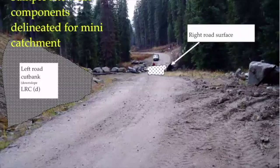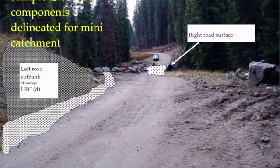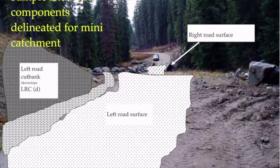When we look at this site example, we can divide the site into components. We have cut banks, road surfaces, ditch lines, more road surfaces. Each of these components has a predetermined rate of erosion, and each has an estimated surface area. By multiplying these two together, we can calculate the volume of sediment that will be generated at this site by those components. If all the calculated volume runs directly into the stream, we say that it is all connected 100%. The volume of erosion multiplied by the connectivity provides a measure of sediment actually reaching the stream and thus impacting water quality.